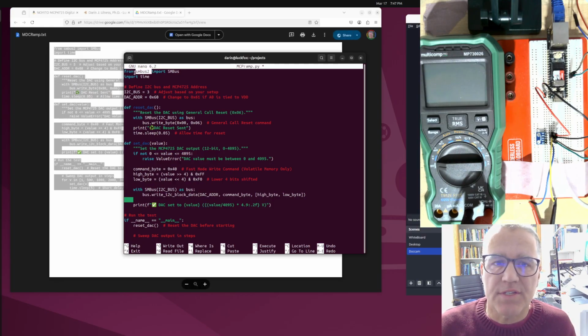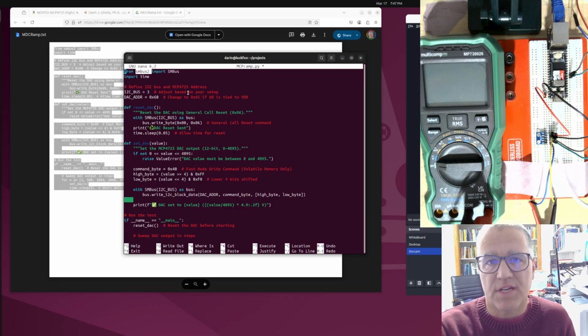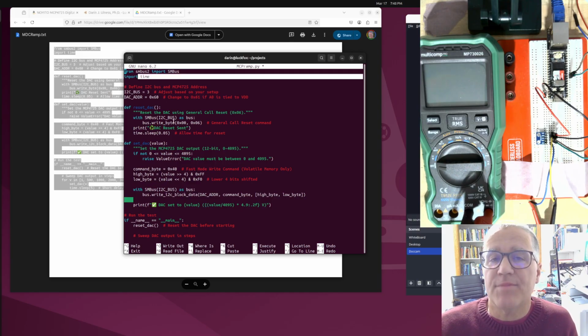So all we need is SMBus2. Now I'll note this if you didn't catch in the previous lecture series, the LuckFox tutorial will have you install SMBus, but I found that didn't work for me, so I had to use SMBus2, and then everything seemed to work just fine. So we're using SMBus2 and just SMBus. So we don't even really have elaborate I2C control, just this very baseline package here. Then we import time. This is just to delay for the 5 seconds.